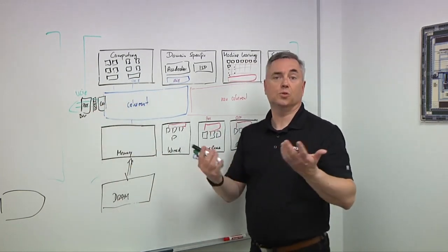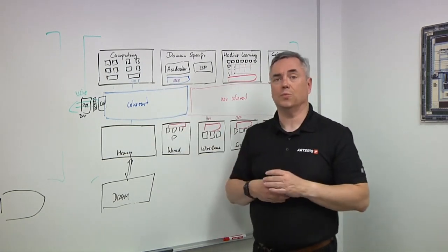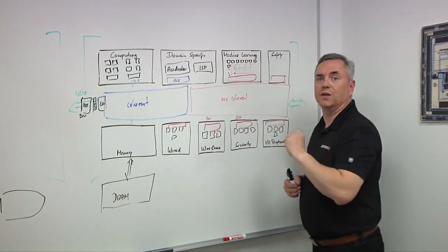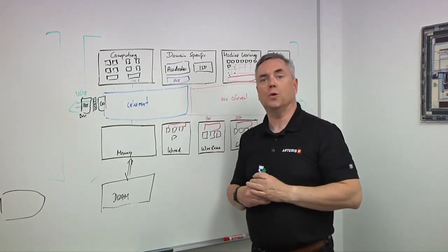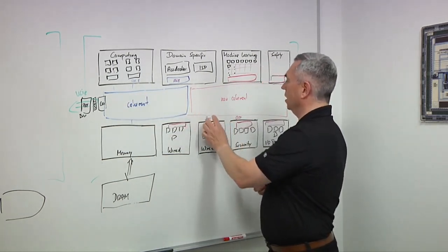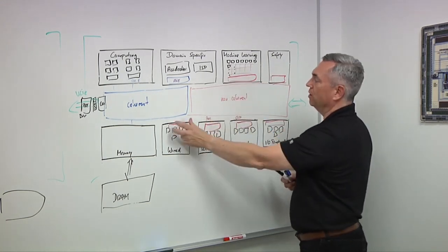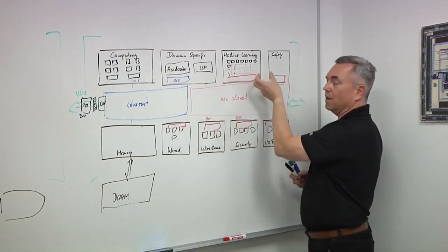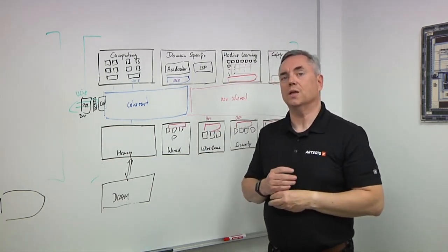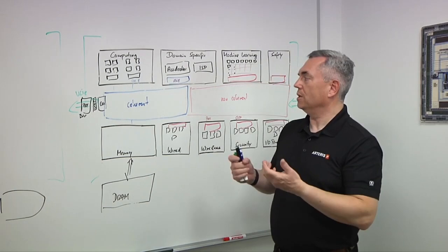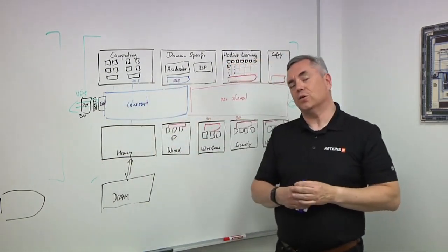That's why we see different topologies. And that's very important in our NOCs here. We support different topologies. We go from mesh and FlexNOC here to various asymmetric irregular topologies, where you can basically decide, I have a very fast line going in here to the fast wireless or the fast wired, but I have a slower line going on to some peripherals or other aspects of the design. So that is all becoming a very important aspect as you plan that across chiplets.